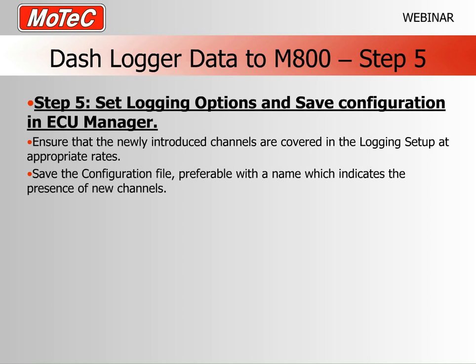Okay, the final thing you need to do in the ECU manager is the same as you would in the dash manager, which is firstly you must set which of these channels you've added you'd like to log. It's a little bit pointless to have them if they're not logged. Of course, they can be used for engine control as well, but it's worth remembering to set the logging up as well. And finally, you would save the configuration file and make sure you send it to the ECU. Now, our habit is normally to give the configuration file a new name or a sequential name or a slightly different name, just so that we know what's been added and why it's there.